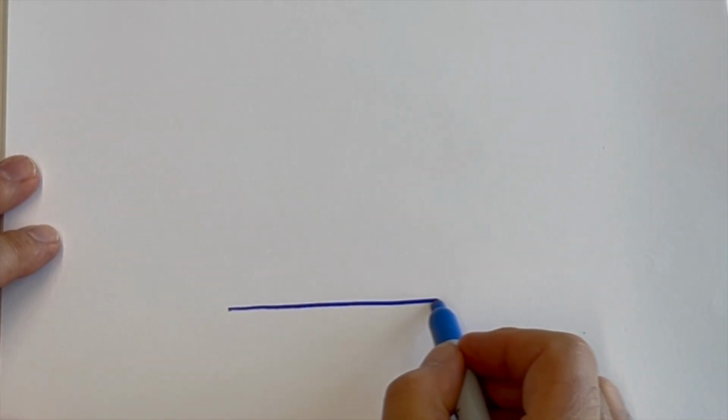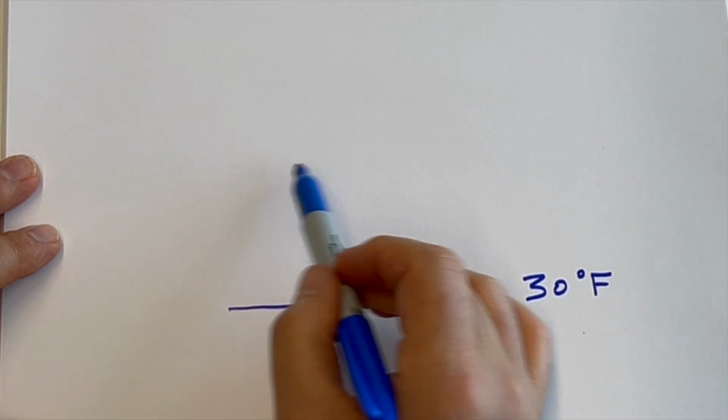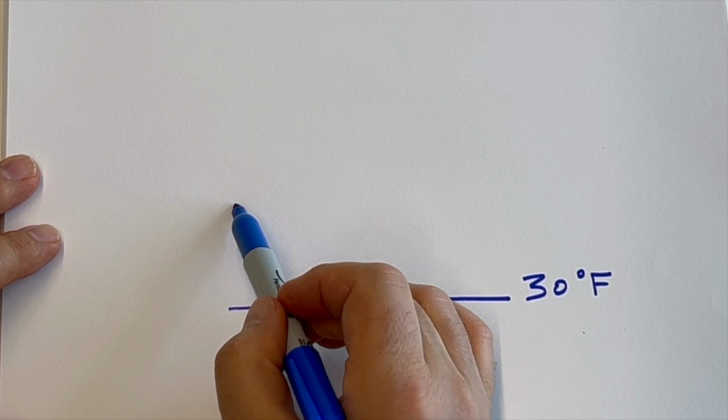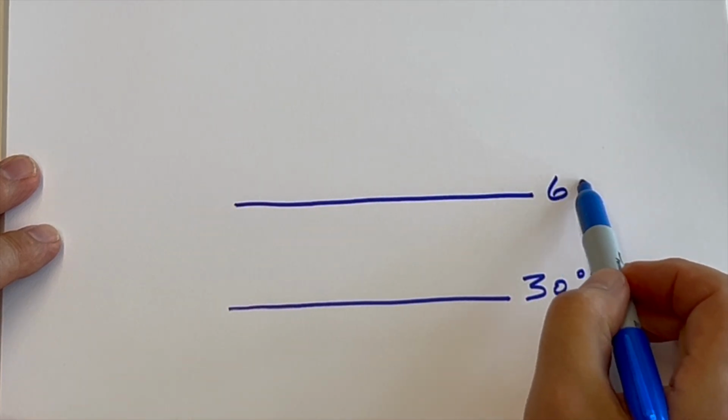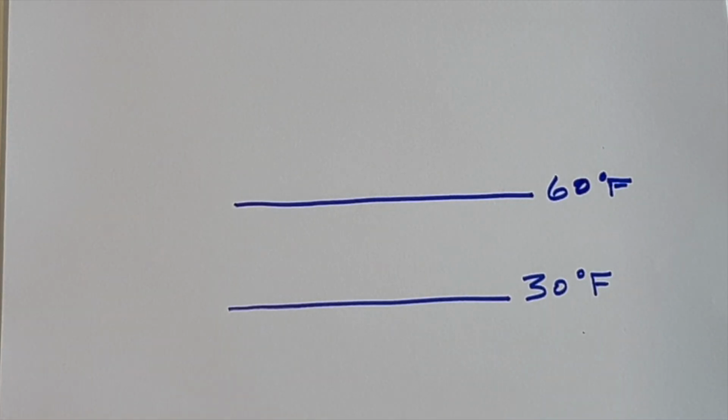Okay, through this lens of temperatures, let's look at the effect of reducing the temperature in winter indoors, reducing the indoor temperature using a setback mode. So outdoors will be our typical 30 degrees Fahrenheit. Indoors, instead of running at 70, let's run it at 60 degrees. What's our refrigerant temperatures? We'll use our rule of thumb.